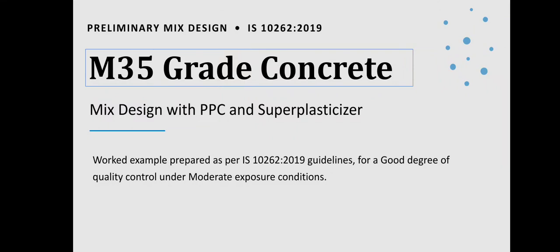Hello everyone. In this presentation, we are working through a complete mix design for M35 grade concrete using PPC, Portland Pozzolana cement and a superplasticizer following the IS 10262-2019 method. This is a full preliminary design start to finish for good quality control under moderate exposure.